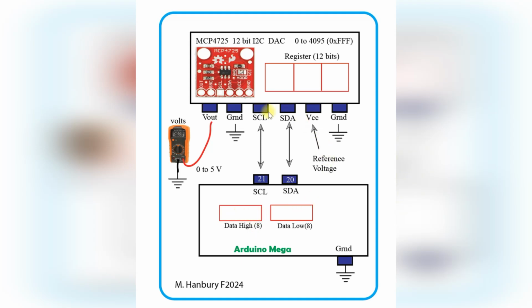You're going to be connecting your PicoScope to these 2 signals, channel A to the clock and channel B of the PicoScope to the serial data so that you can monitor what's happening. So that's the hardware. And then the pin that you're going to connect the Elvis meter to is the V out pin with respect to ground.